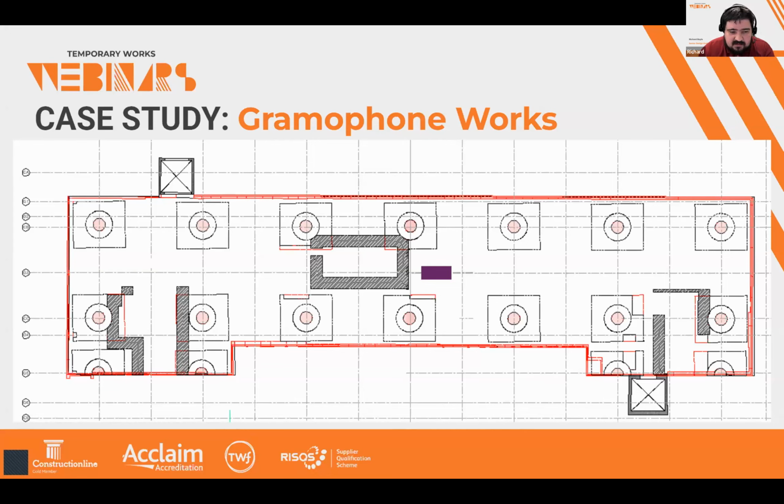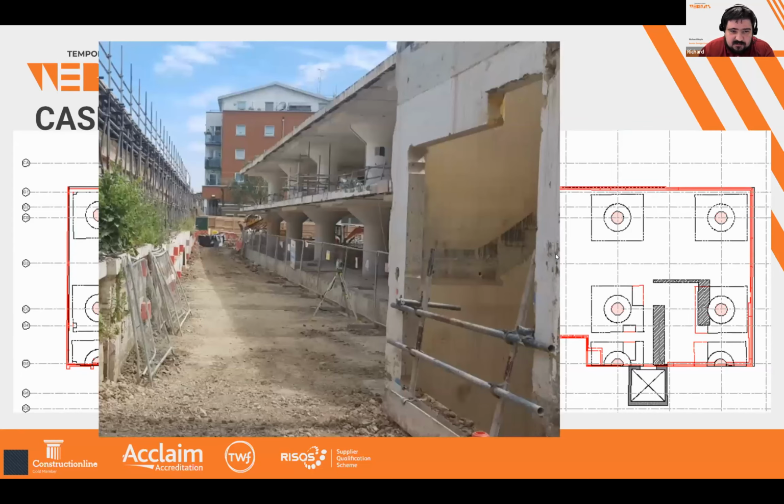And the building initially had two large towers, one at the top left, one at the bottom right. Originally, you might think that they might be providing some stability to the structure, but alas, no. They were completely separate and self-standing. So it was the columns themselves that were giving support laterally to the building as well. And the walls around the perimeter, we discovered quite quickly, weren't structurally needed either.